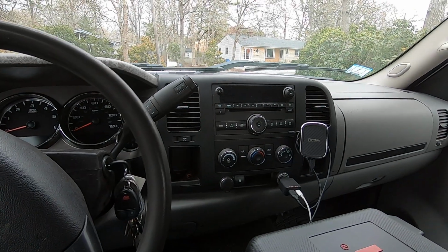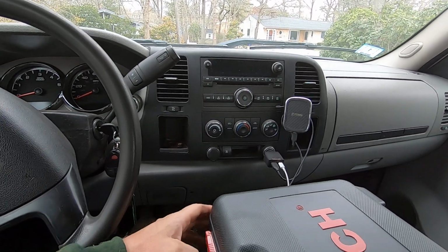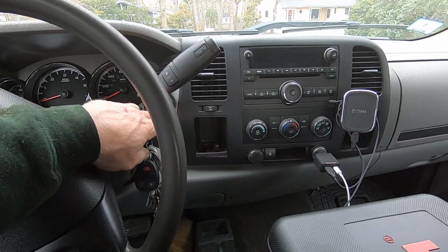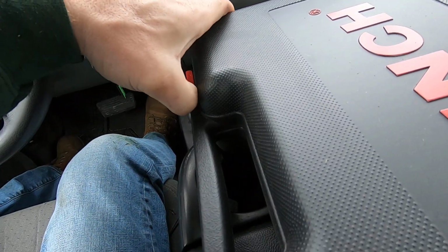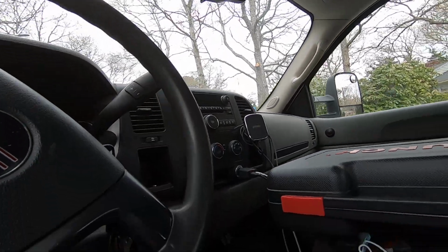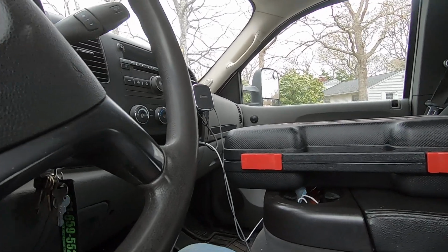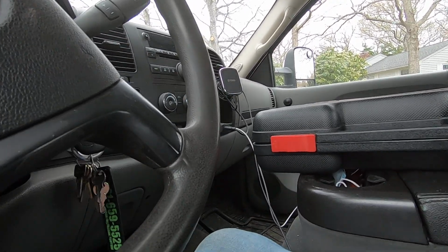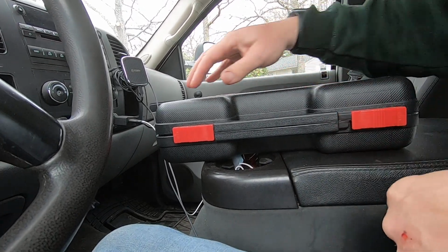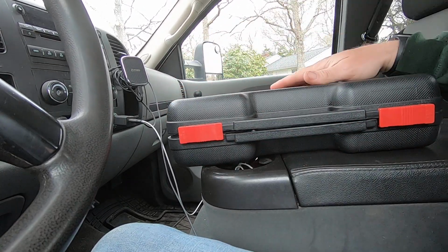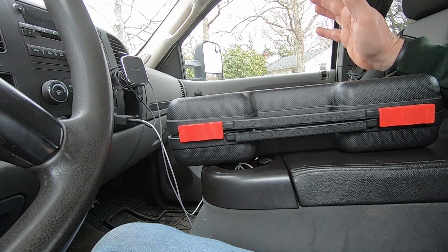All right, 2009 GMC 2500 HD with a 6-liter gas. Just got my check engine light to come back on. I thought I fixed it. I had a purge solenoid bad that was staying open, and then I also had what I thought was a loose connection on the vent valve because it wasn't holding pressure. And I ended up cleaning the connections and it was working fine.